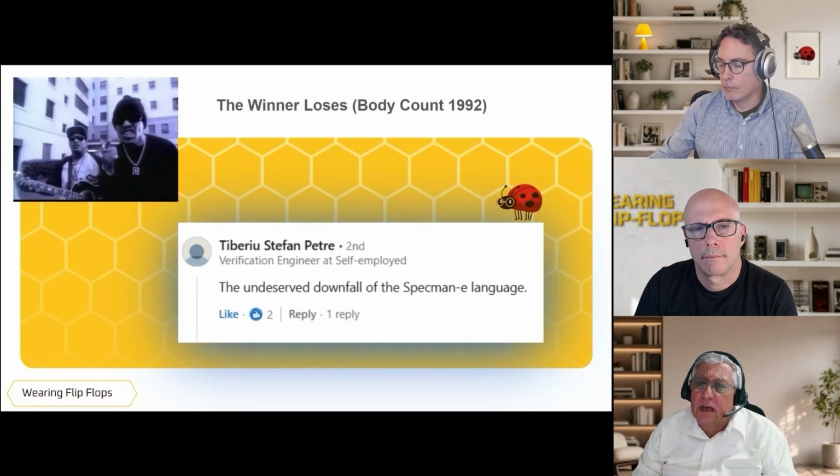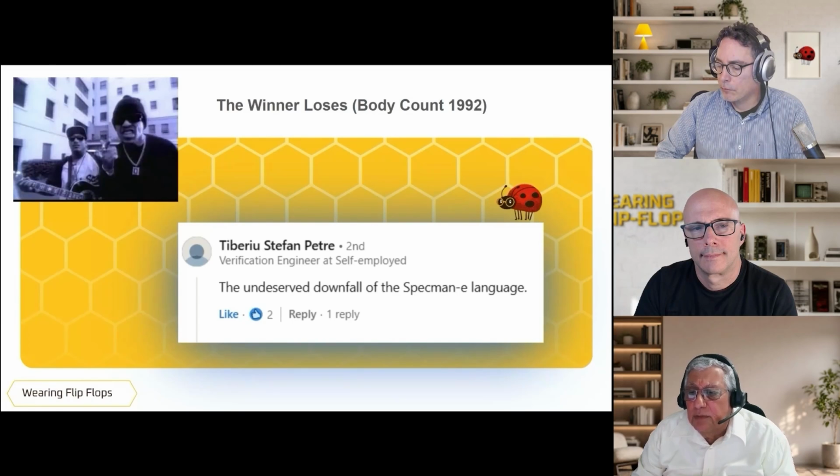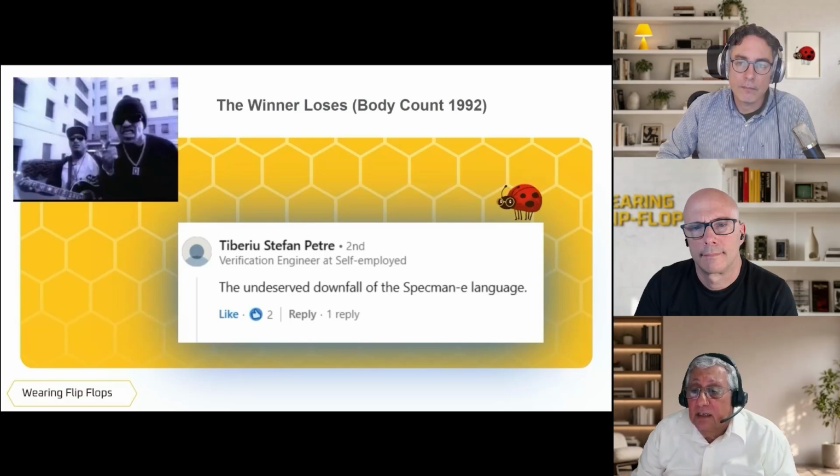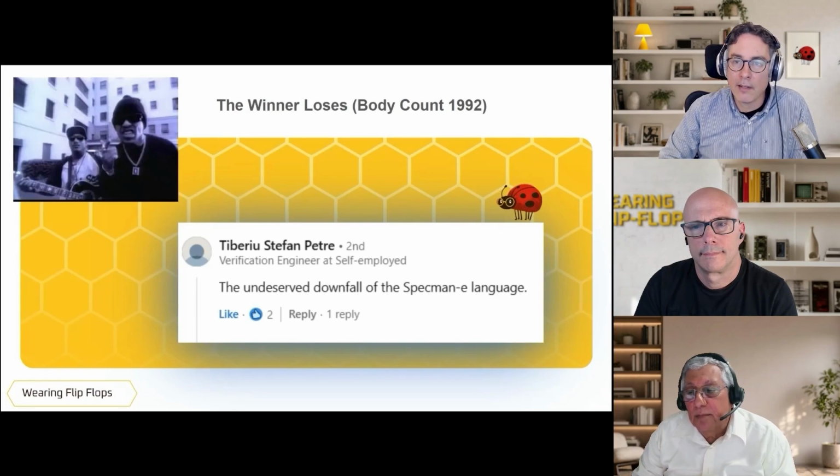Well, it's hard to say. Let me say this. I think anything that you can do in Specman, you can also do in UVM eventually. The real question is how many lines of code and effort you want to invest. Everything I said, including the AOP, has a solution in UVM with the factory, so you can't say that you can't do it. The real issue is how many lines of code you're going to maintain, and how many bugs you're going to introduce when you write the factory code and all the macros.